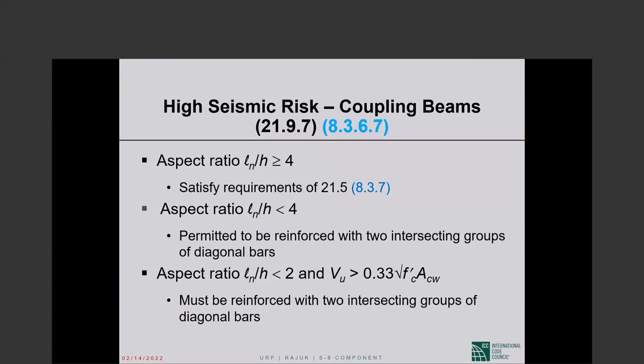The thing about coupled shear walls is that the shears at the ends of the coupling beams add up to compression on one of the walls and tension on the other wall that is coupled. This tension-compression couple resists a part of the overturning moment, leaving only the remainder of the overturning moment to be resisted by the shear walls themselves. So we can spare the shear walls from damage by sustaining damage in the coupling beams, which are much more easily repairable. So these are pretty popular.